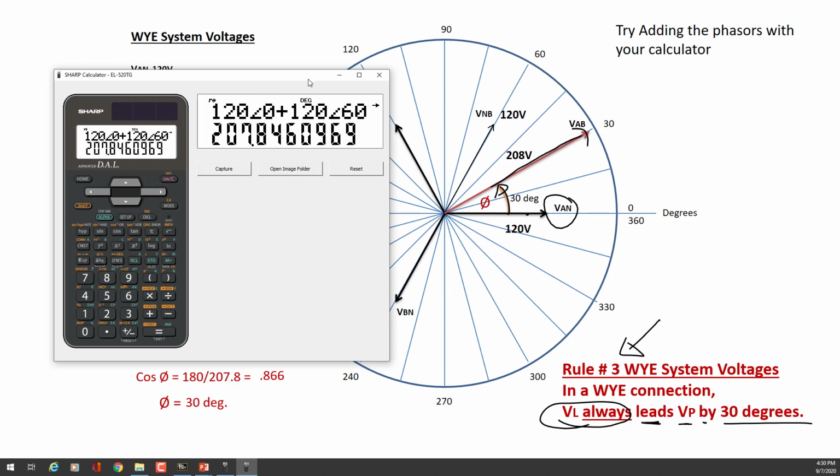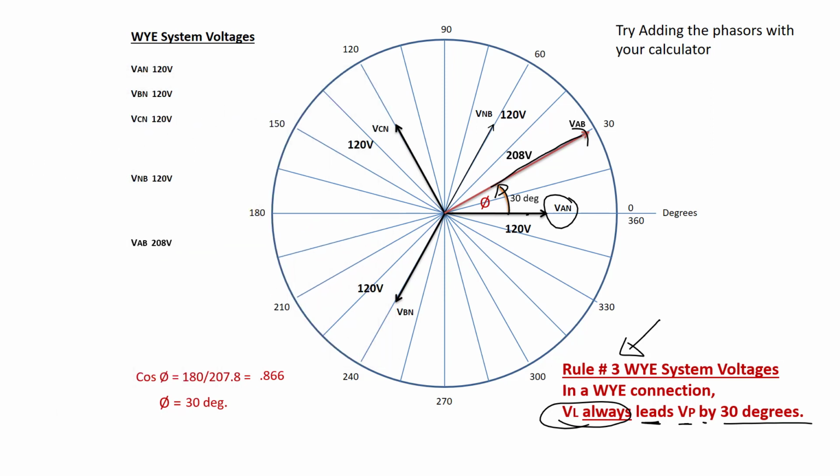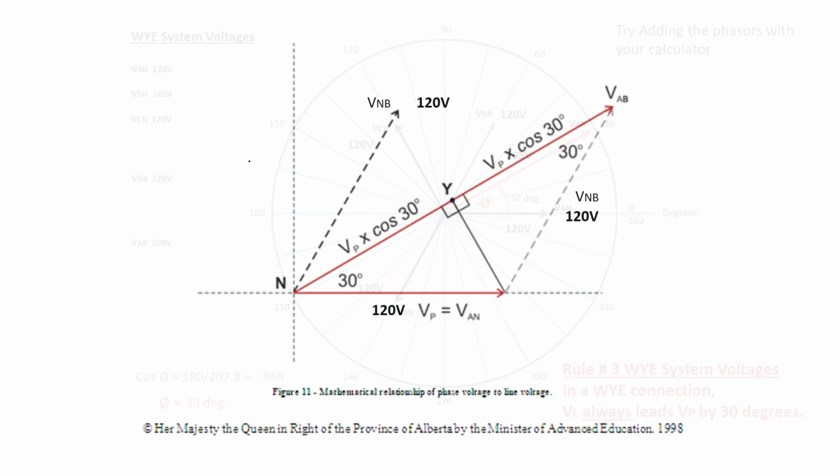For us doing cosine and sine charts, the horizontal vertical charts, the entire time, we are going to be adding up tons of vectors. We're going to be adding up voltage vectors, current vectors to find our neutral. And when we get to delta, we're going to be adding up phase currents to get our line current. So it's a real big advantage and time saver, very accurate as well. So I suggest you learn how to use that system and know how to break it down if you had to with your cosine sine chart and add your vectors up that way.